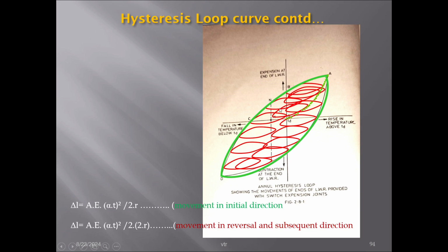As I already know, pretty well, we are providing an initial gap of 40 mm, and with reference to the reference line, we have 20 mm on one side. So a 20 mm initial gap at the time of TD temperature, and from there, if there is an expansion, suppose upside is 5 mm and downside is 10 mm contraction. With 5 mm expansion, what will happen? Once the expansion is there, tangential side expansion, the gap will be reduced. That means 20 minus 5, 15 will be the gap.